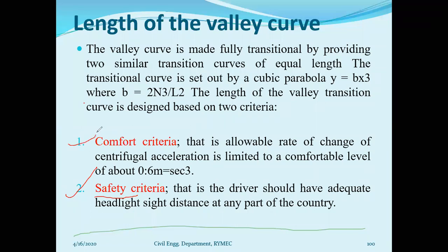Right? So when you are talking about this comfort condition, as I told you just now, this is your valley curve going down. If I am moving in the downward direction, centrifugal force is developed. Along with the centrifugal force acting in the downward direction, you get an additional force, which is the self weight of your vehicle, providing additional pressure on your suspension system, as I told you. For that reason it becomes discomfort. As the centrifugal force increases, it leads to discomfort to the road users.